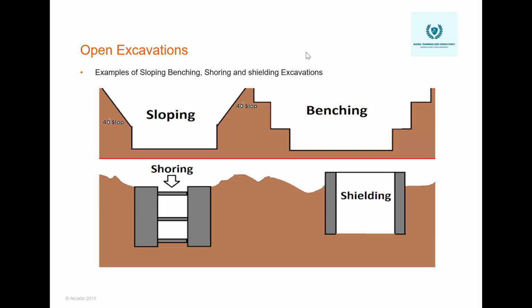We have to identify. How to identify? We may have a cable detector, a machine or a device which we use to detect underground utilities. We may have radar mapping to identify. We may have previous drawings available showing some underground utilities. We need to check those drawings, and we can do trial pits. If any other source is not available, we will do some manual excavations.